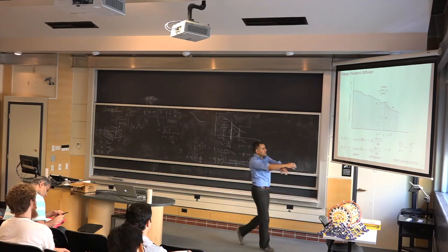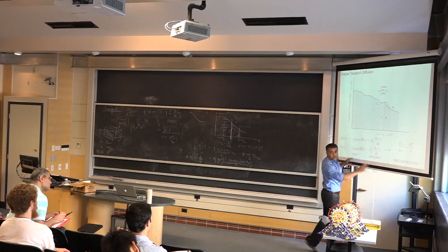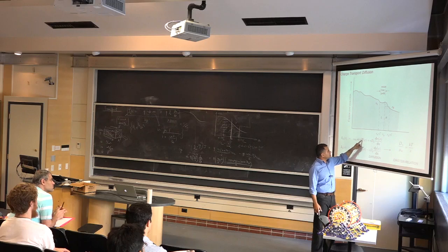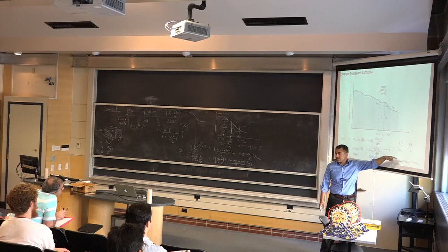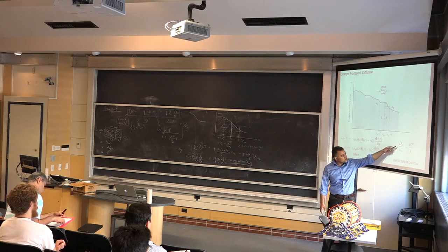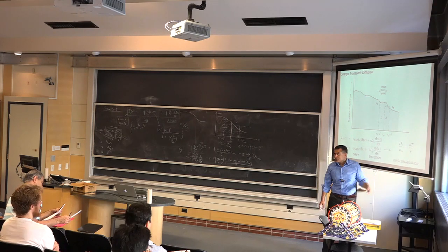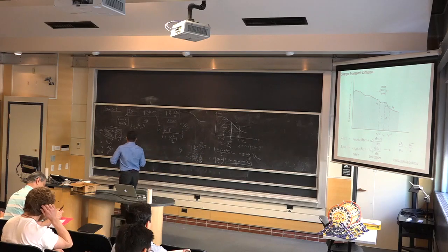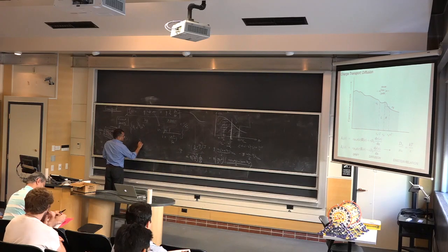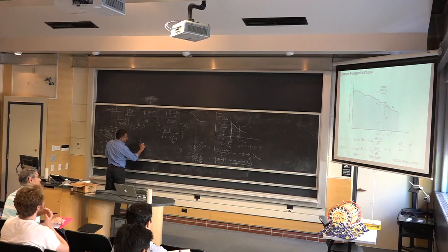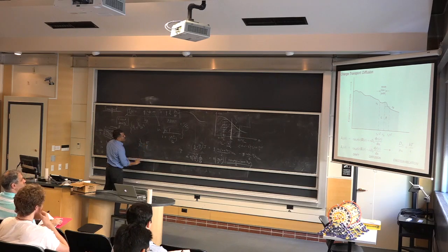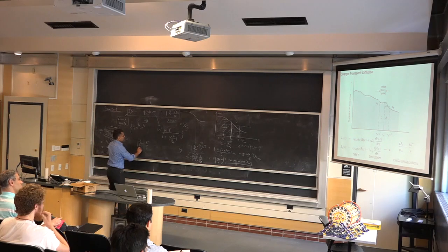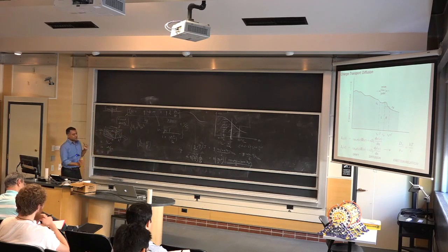And at some point it's going to reach equilibrium. And when is that equilibrium? When these two terms become equal. Right? And when they become equal, you can equate mobility times field and all that. You get what's the Einstein relation: the diffusion coefficient divided by mobility is kT by q, or kT by electron charge. That's where it comes from. The diffusion coefficient is related to the mobility by kT by q. The Einstein relation. So, okay, it was a long detour, but that's all I'm going to say about transport now.